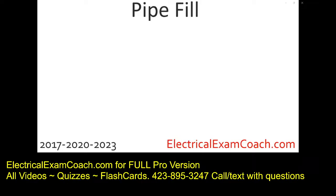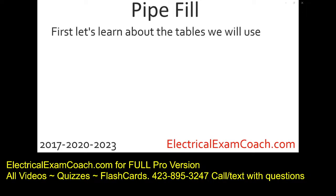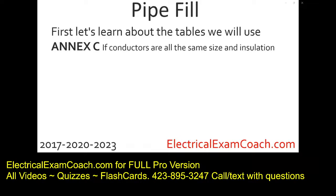This first lesson is going to deal with if all the conductors are of the same size and insulation type, meaning if they're all number 12s and THHN. The next lesson, lesson 7.2, will deal with if we have different sizes of conductors and different insulation types, meaning if I have 10s and 12s inside of the same conduit. Let's go ahead and learn about the table that we'll use if they are all of the same size. We're going to use Annex C.